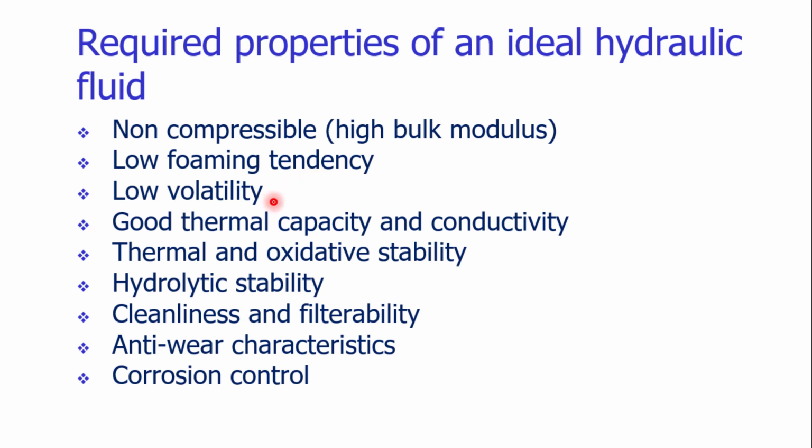It must be less volatile. The ideal hydraulic fluid should have very good thermal capacity. The heat capacity should be high, and it should have good thermal conductivity. If the conductivity is low, it will get heated up, and that hot hydraulic fluid will lead to the failure of the system. It will damage the system.